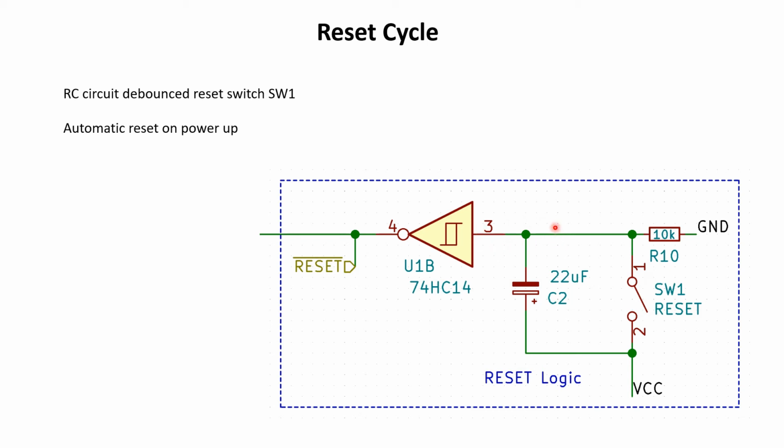At the beginning the voltage will be high enough to be above the trigger value of that Schmitt trigger, and the longer this capacitor charges, the lower that voltage will be, and finally it will close that Schmitt trigger, thus letting that reset line go high.